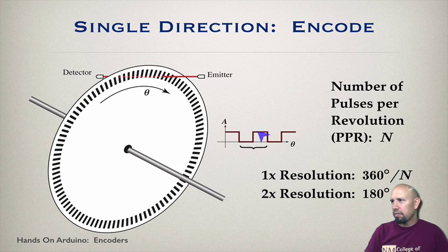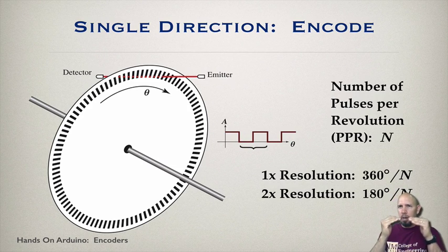Basically what happens as you rotate this disk, or the whole shaft with the disk on it, we get pulses. Now the pulses out of the detector are never actually this clean. Usually the signal that comes from the detector goes through a little bit of circuitry to square up the wave, so that you get a nice square wave with a 50% duty cycle. That circuitry helps to balance the thing out. But that's basically what you get. As this thing rotates, you get pulses.